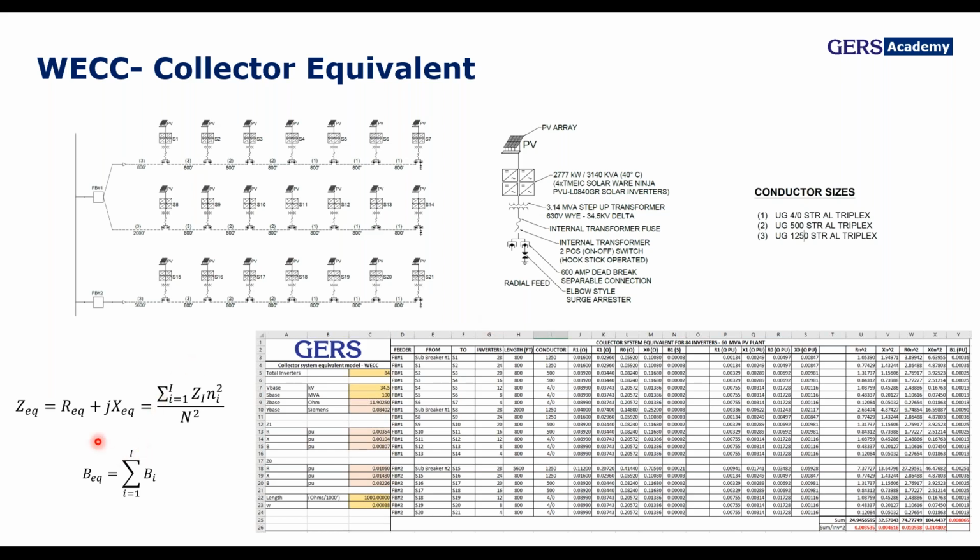So the final values are considerably big in comparison with normal conductors, but in fact this is just a mathematical model. And the parameters related to the capacitance are relevant in the sense that they are connected with using underground cables, and you know that in underground systems the capacitance reaches high values.